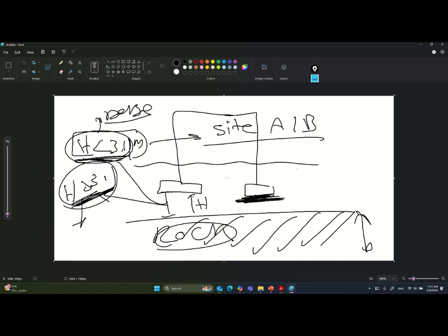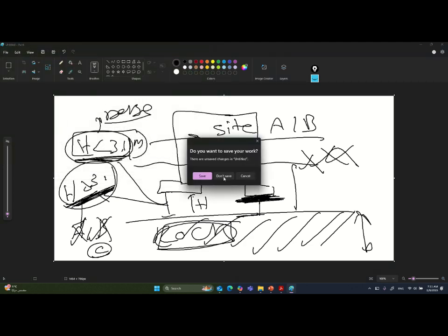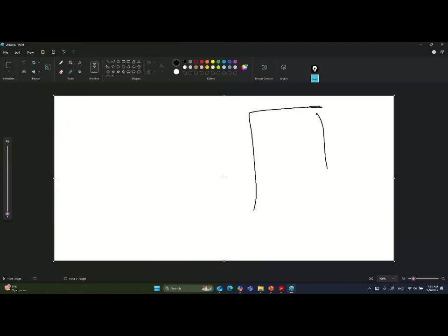So I am measuring from here, not from the ground, from the bottom of the foundation to the top of the rock soil. If it is more than that, then A and B will not be applied, so you can assume C. It is very important to note, because in some cases he will give you an example or a question where you can determine the site class.